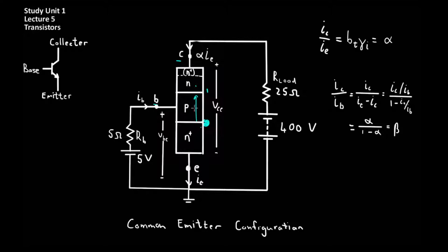Of course, this is not the case, and two things are done to ensure that the electron carriers get across to the collector. Firstly, the base is normally made quite thin, and secondly, and more importantly, carriers can be injected into the base to make up for the deficit in carriers which recombine in the base of the transistor.